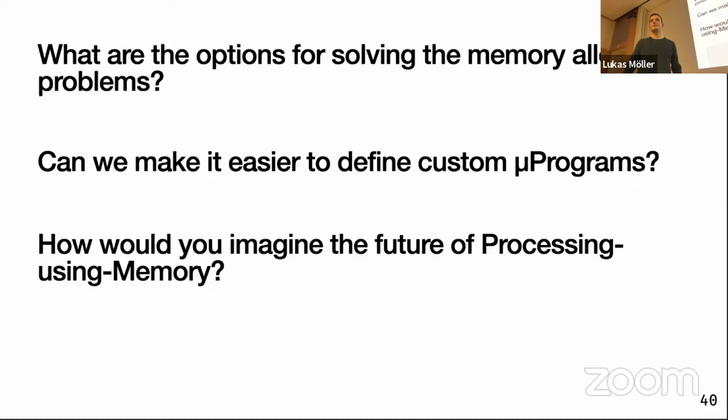The only question that comes to mind is that it's really great for bulk operations or parallel processing, but if you have an application with a huge context, for example, it uses 60 registers, how do you access 60 values concurrently in such a DRAM-based system?